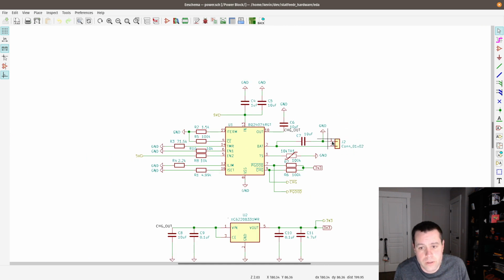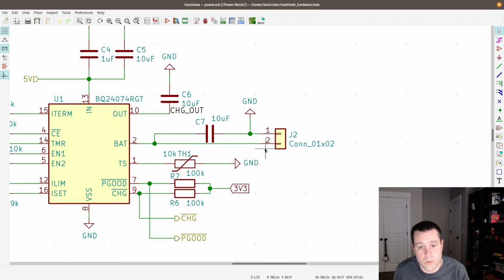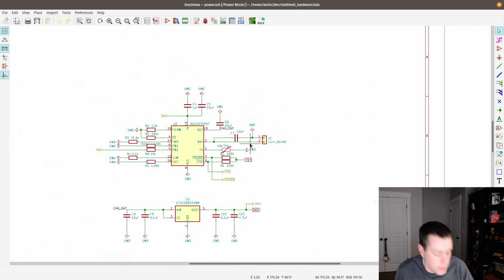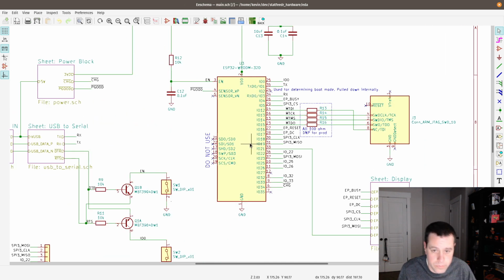Right from here, yeah, because we're not even at three. This is a regulated 3.3 volts that comes out and powers. I'm saying take the battery straight off of pin 2 here. Let's zoom in, like right here, and feed that into an analog to digital converter pin, an ADC pin on the ESP32, to get a reading.